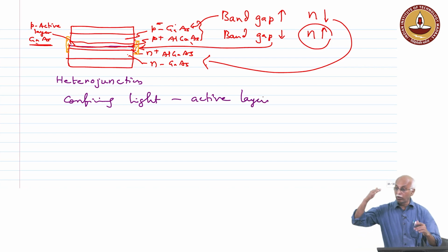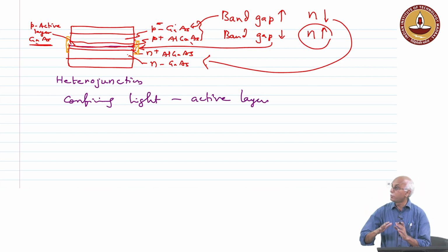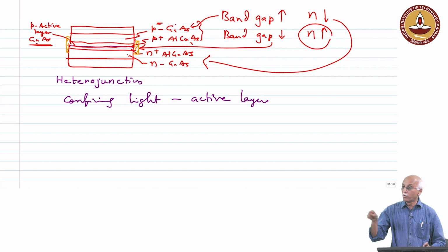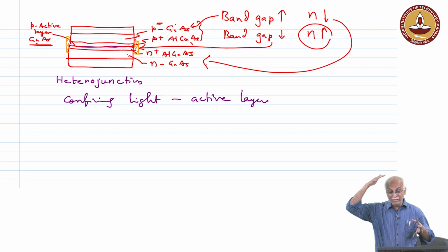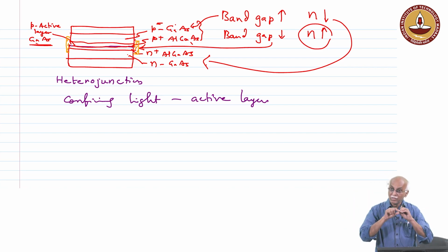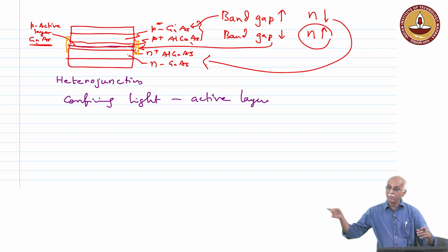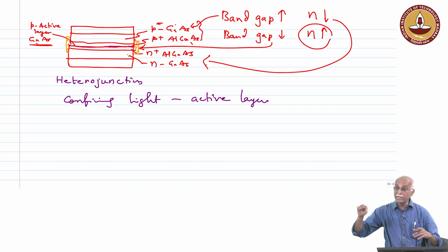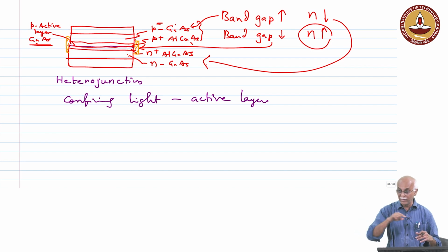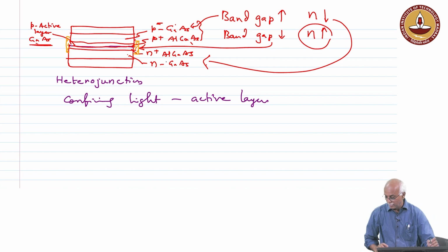the threshold required for laser output decreases, because photons will not escape now, and spontaneous emission will start reducing because stimulated emission will be much larger. Photons will travel along this path, get feedback, and start removing excited electrons to get more and more photons along one direction, along a straight line, edge emitting.